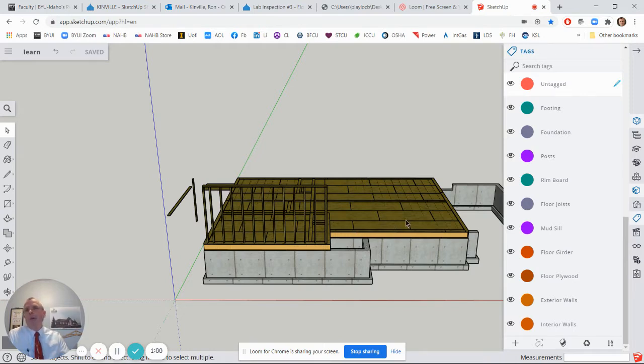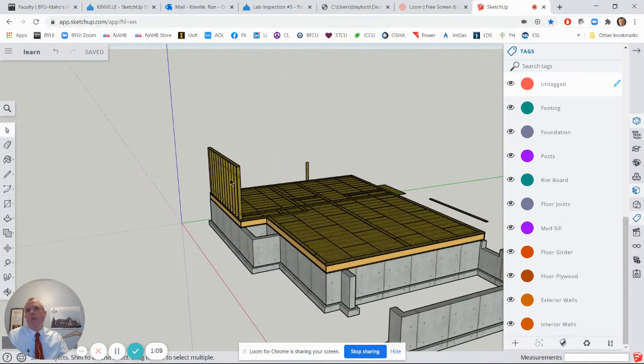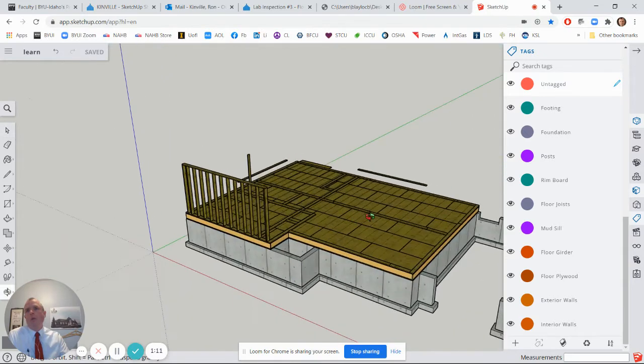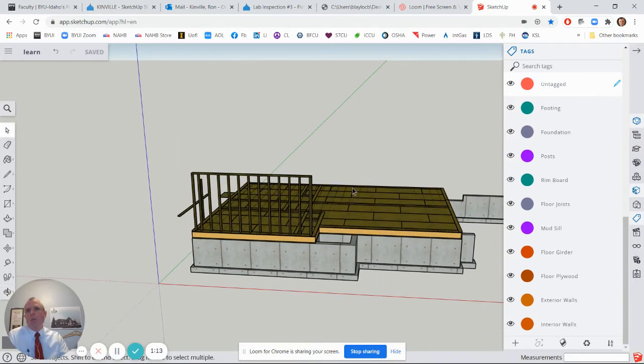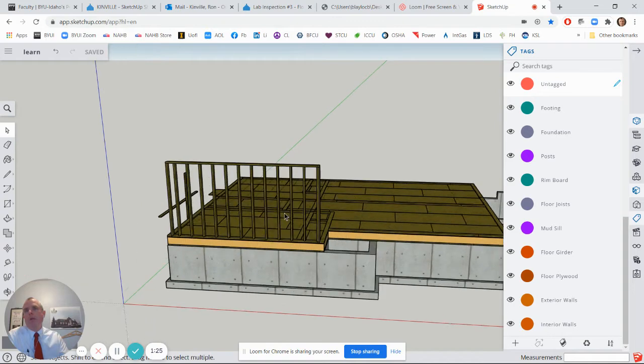In this house, we don't have any real big openings. We have a 6-foot window, which is fairly substantial. But we also have 2x6 walls that we're framing with. The width of these walls is 5.5 inches. We want a header that is 5.5 inches wide so that it is the same size as the wall width. Headers don't have to be the same size, but it makes it nice and convenient for framing. So that's what we're going to do.